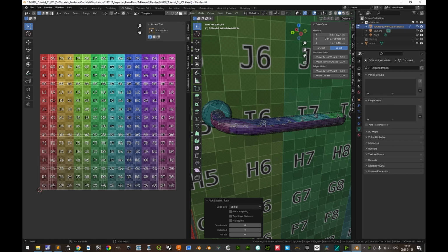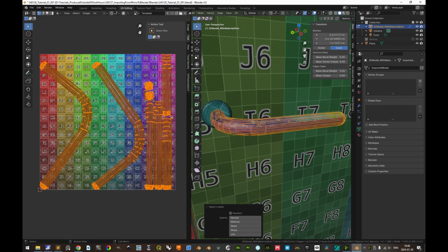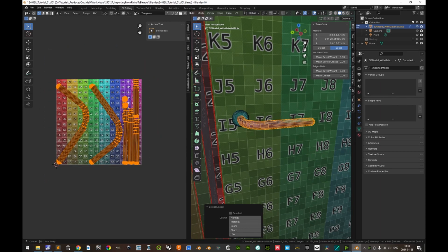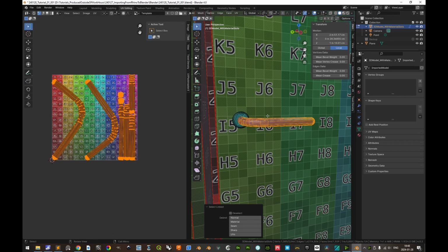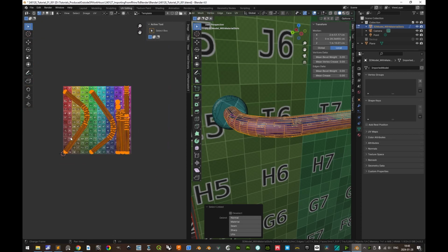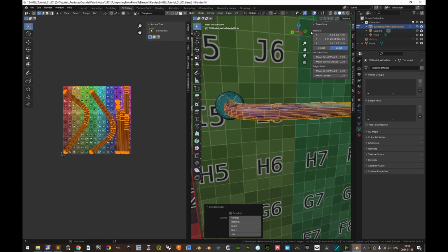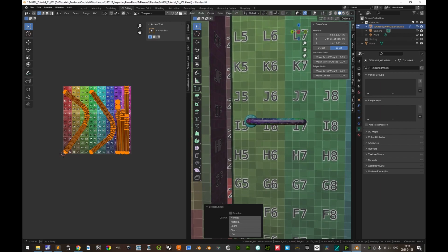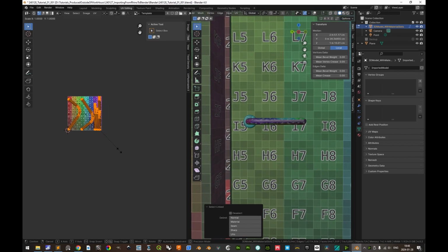All right, let's click to link select all of those again so that we have the UV island selected here in the UV editor. And then now the important thing is to make sure that the scale of this, because now it has been unwrapped to fit the UV 0 to 1 space again. So then we can temporarily toggle the overlays again. And then let's see here, if we look at it from this place perhaps, then we can just do S for scaling here. And it should definitely not be larger, the UV islands, it should be smaller.